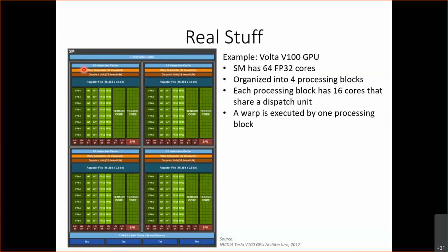No, these are in-order pipelines, not out-of-order. Remember, we said in the first lecture that out-of-order execution is to optimize for latency. But these GPUs are optimized for throughput at the expense of latency. And what that means is we don't want to invest hardware into out-of-order execution. We prefer to invest it into adding more cores. So these are all in-order cores.